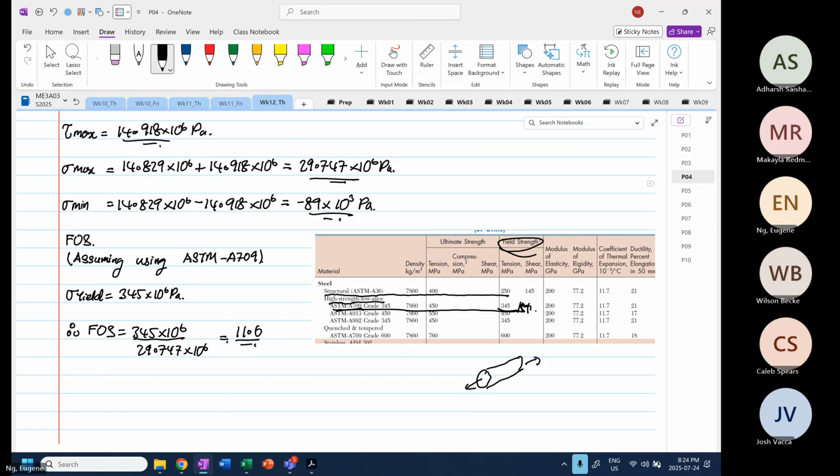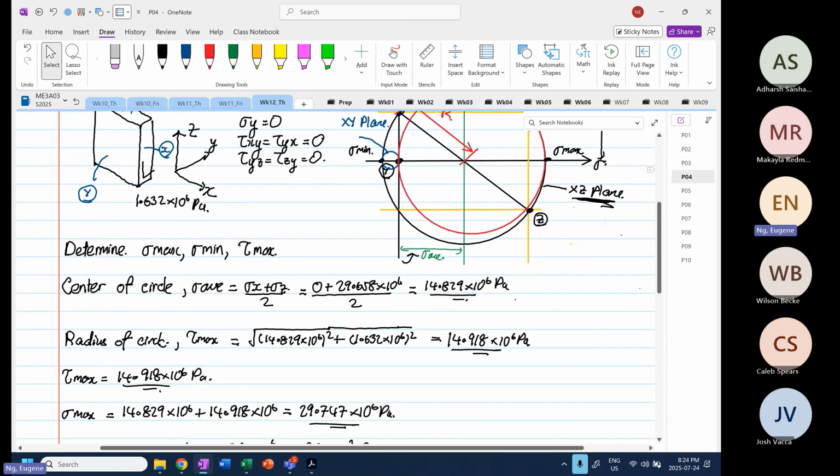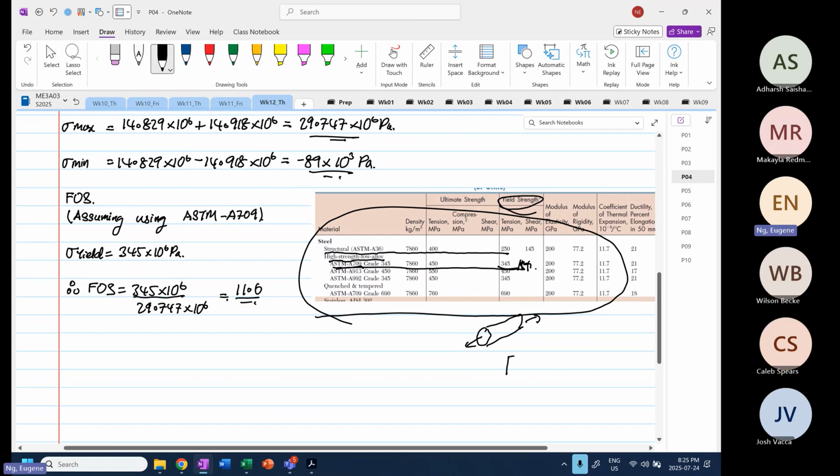One direction, right? So how to relate a combined loading into an axial loading that is found in the materials handbook? They only do axial loading. They don't do loading like what you have over here. So the only way to do this is to use what? Mohr's circle to determine where you have zero shearing stress. Because when you have a uniaxial tensile test over here, the shear is also equal to what? Zero. Again, this is true engineering work now. This is what a typical mechanical engineer has to do.